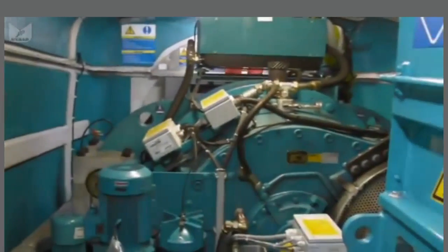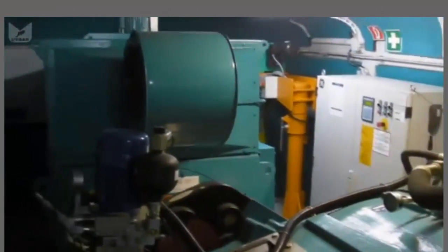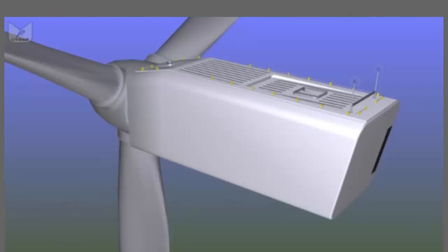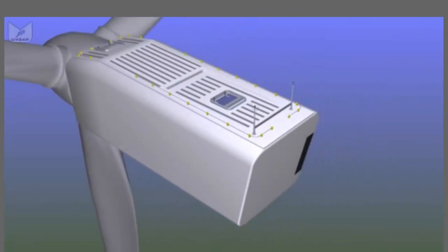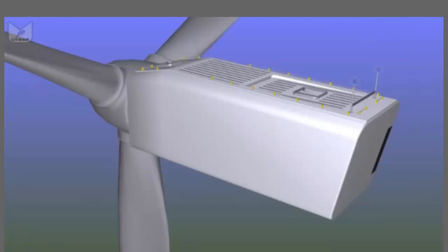the same as we needed in the small turbine. Gearbox, generator, possibly a transformer, all in a fiberglass box. And in our example, we're looking at a typical design used by a number of manufacturers where we have a nacelle that's 3 meters high, 2.5 meters wide, 7 or 8 meters long. It's a fiberglass box about the size of a site hut.